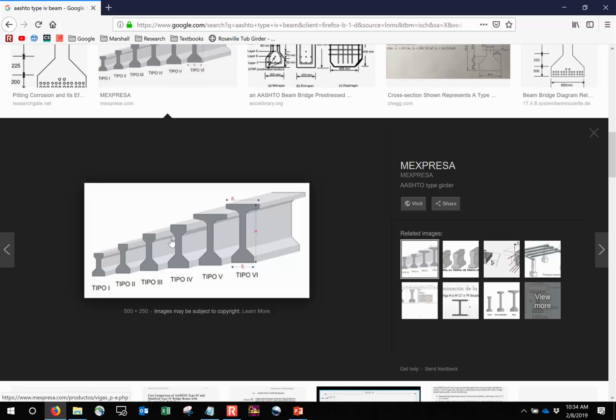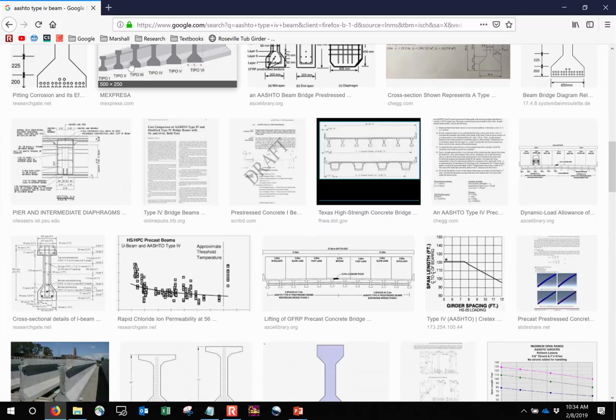One of the nice things about a lot of these weird, wonky cross-sections is because the geometry is a little weird, a lot of times your moment capacity and things like that are already calculated for you as an engineer. You'll find these design tables that say, AASHTO type 3, here's my concrete, bam, here's Mn. Those are lookups if you need. But if it's something really weird, it's just centroids. This is good stuff. I like this. Any other questions? Cool.